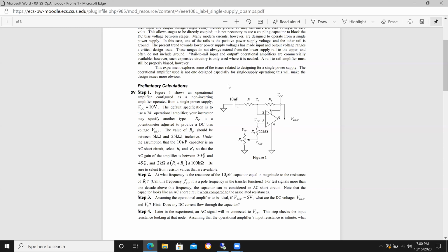So when you calculate those 2 pole frequencies, you're going to have 2 low frequency values. You got to pick the higher of the 2. So again, like I said, one might be, say, 5K, the other one's 10K. Then usually, as a rule of thumb, you'll go like an order of magnitude above.